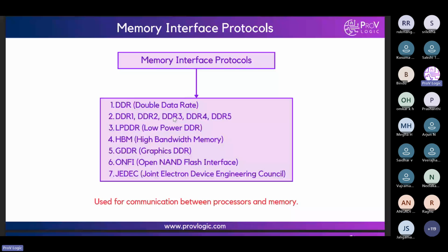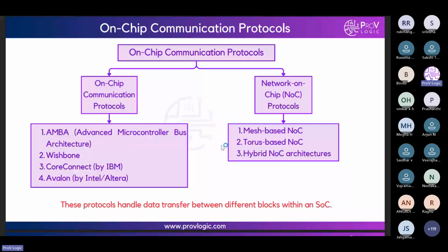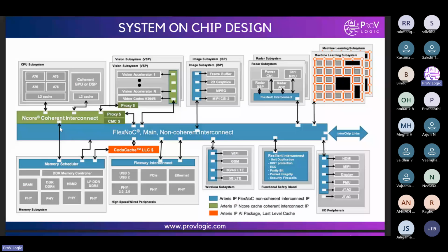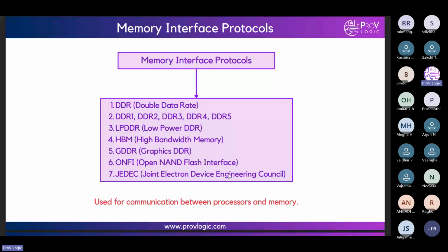That means one processor related project, one memory related project, and the remaining protocols. So you will be learning the DDR project also, for RTL design and verification. And LPDDR is like an SDRAM. HBM, GDDR is graphics related DDR. These are not open source. These are designed specifically based on their own requirements.